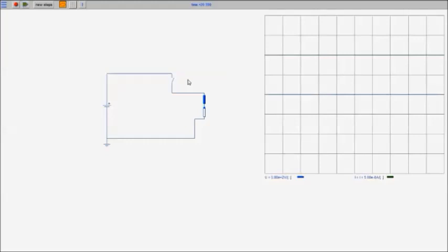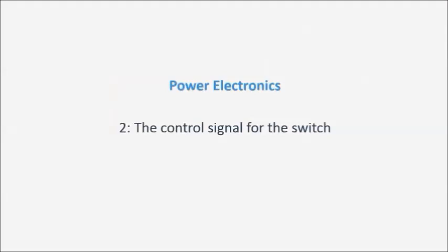And what you also would like to achieve is that you do not only switch from 0 volt to plus 1000, you would like to switch from minus 1000 to plus 1000. But then you need a little bit more switches, 4 switches to be precise. In order to control 4 switches manually, it is quite difficult. And therefore, you would like to control these switches electronically.